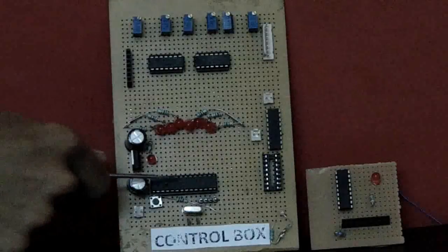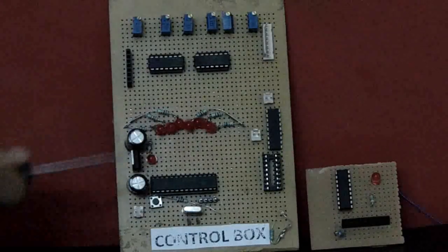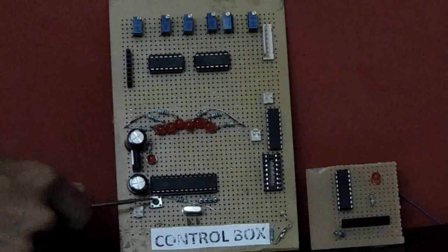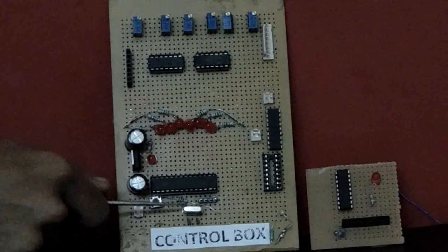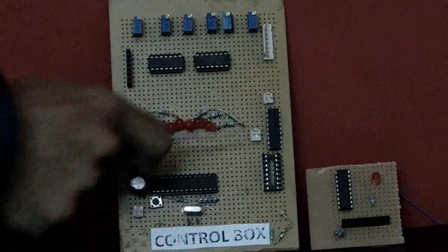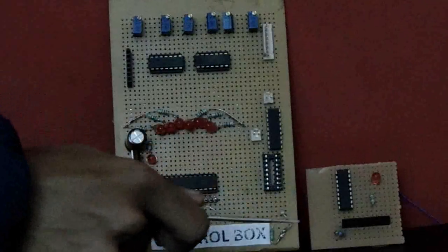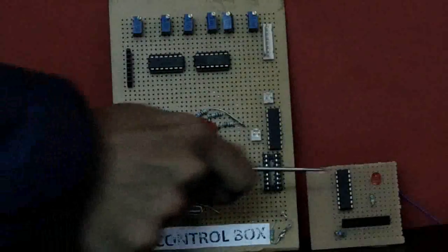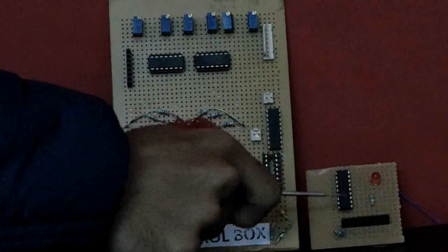The controller used here is the PIC 16F870. It is a 28-pin, 8K memory IC working on a 5 volt supply on the 28th pin. This PIC has been provided a 4 MHz oscillating frequency. The encoder used, HT12E, is a 4:1 encoder. It works on an input supply of 5 volts and is used for serial data transmission. Similar are the attributes of the 1:4 decoder HT12D used.